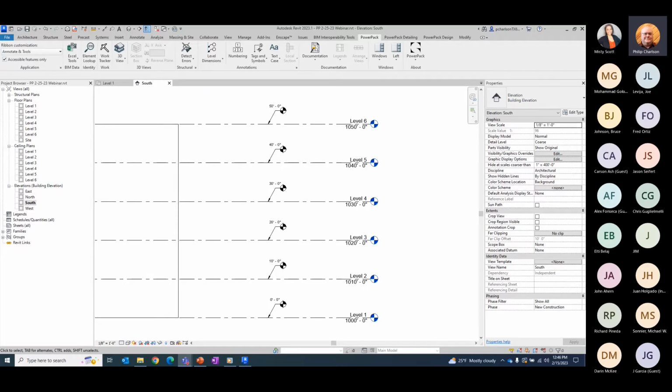I guess are you referring to when I went in and added the shared parameter for the door? Because what that is doing is bringing it into your project, and it is simply applying that to, in this case, all the doors within your project.